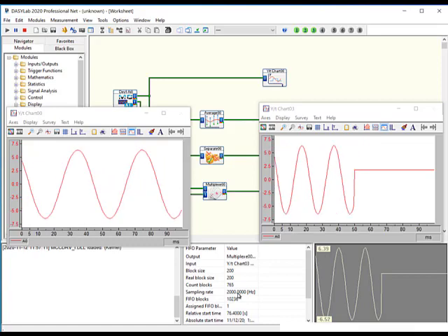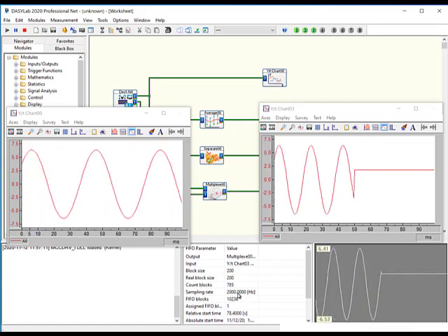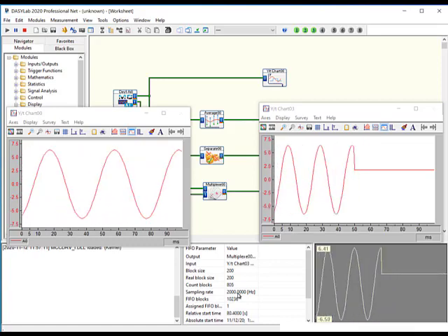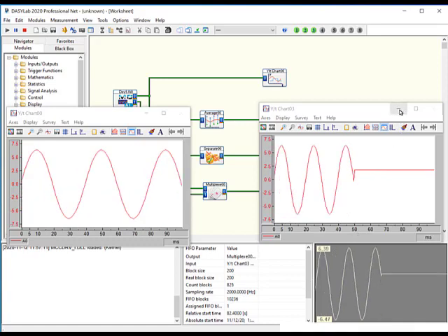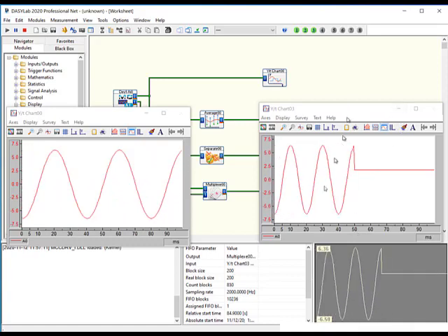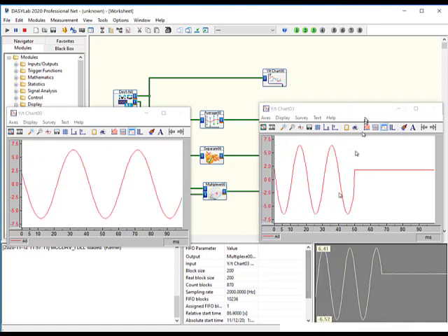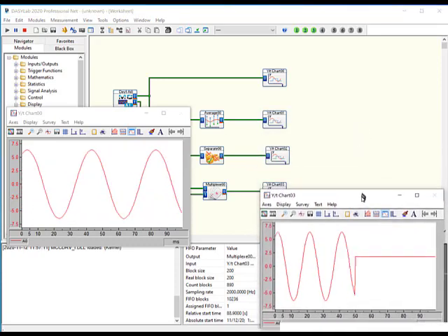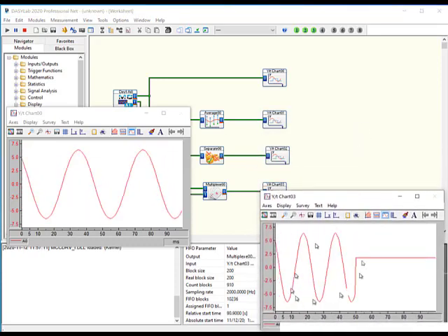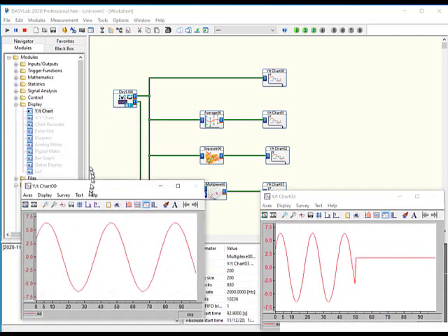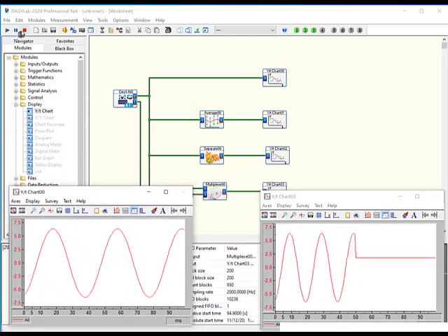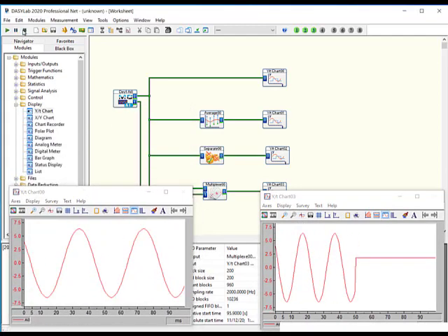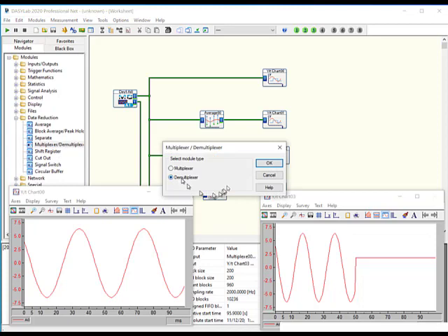This is an illusion. We just create a fat block or a fat wire, but there is no indicator in the DASYLab block that this has been a multiplex channel. So you can now use this like any other channel of data, and if you want to break it apart again further into your worksheet, then you could use the multiplex demultiplex to demultiplex it again.